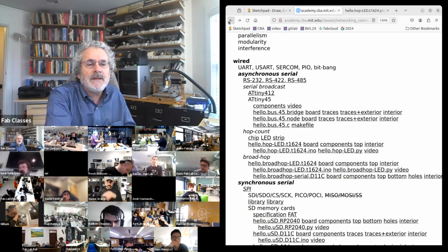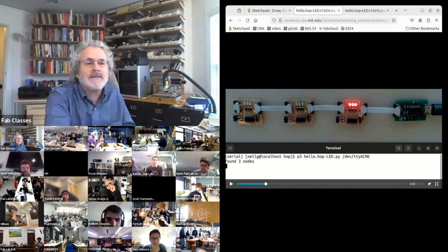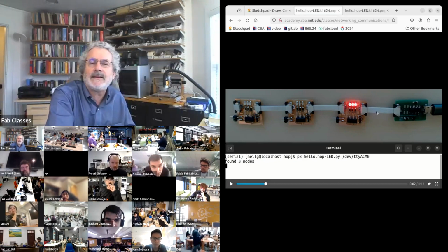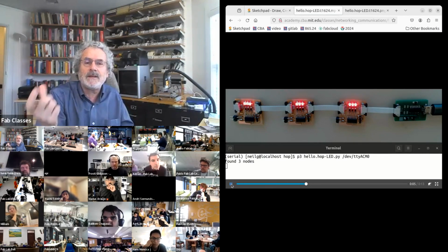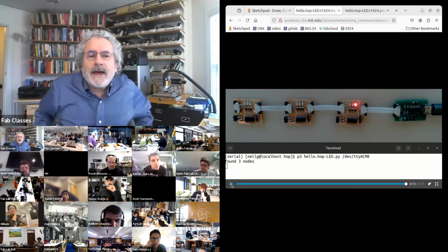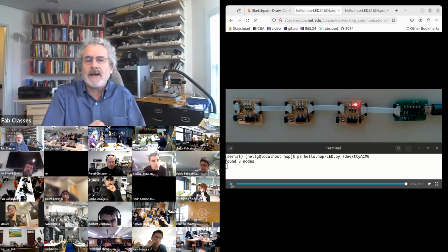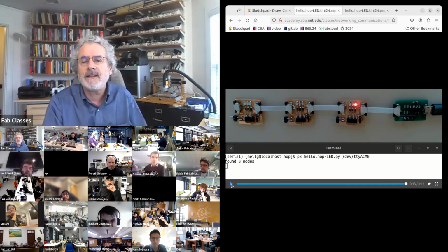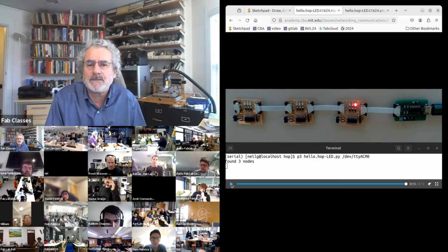If we go back to the video again, let me stop it here. So I started running, found 3 nodes, which means the message went from the host down to the end and back again, and I got my node count. Now I'm going to start sending out messages using the addresses that got assigned by the hop count, and now I can control the LEDs. So now I'm talking to multiple processors, and this frees me from having to assign addresses. I can just start connecting them up, and the hop count will find out how many are there and give them addresses.